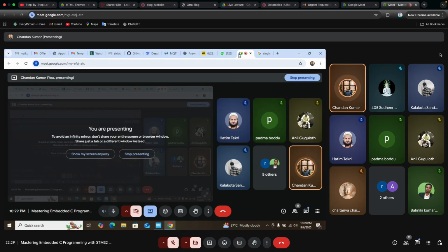Okay, so just write down the I2C data frame. It is the most asked question. Whenever you give an interview or tell anyone about I2C, they will ask what the I2C data frame components are. So just write it, and then I will show you some photographs from Google if I find them. The first in the I2C data frame is the start condition.